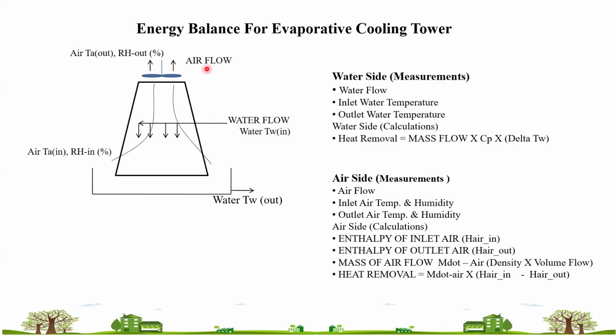There is a particular temperature of that water, and you are getting cold water inside this sump. So heat is getting transferred. The quantity of heat is calculated as mass flow rate into specific heat of water into delta T. So this is your water side energy. Water side heat is dissipated into air. So water side heat is carried into the air, so it has to be equal to the air side.